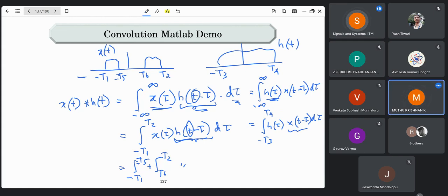In fact, in the discussion of the Fourier transforms, we will see that the moment you represent everything in the frequency domain, the input-output relationship simply becomes a multiplication. So if you know the frequency domain representation of the input and of the impulse response, the output is simply a product of these two. There is no integration. You just multiply pointwise and you're done. Yes, sir. Does that answer your question? Yes, sir. Yes, definitely.